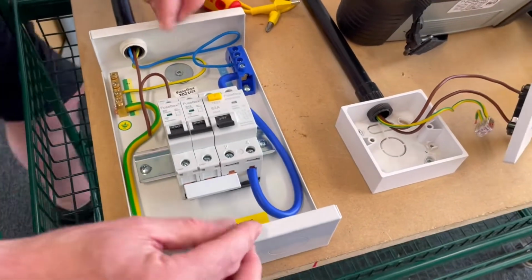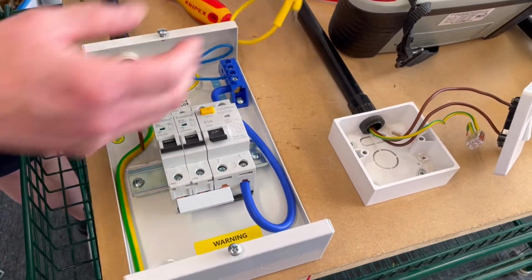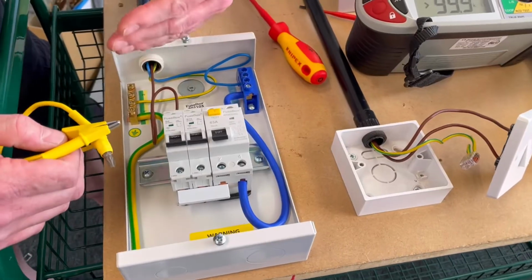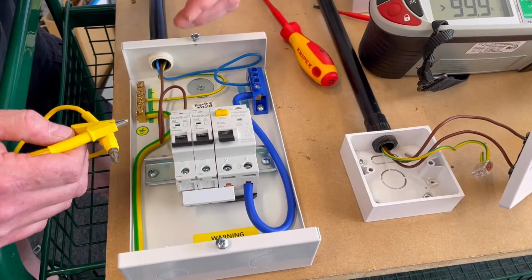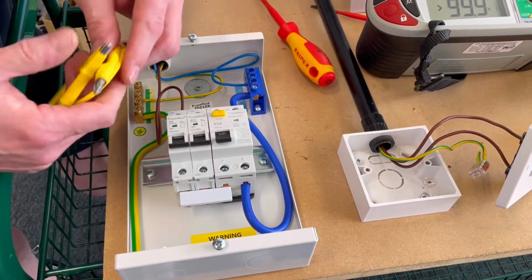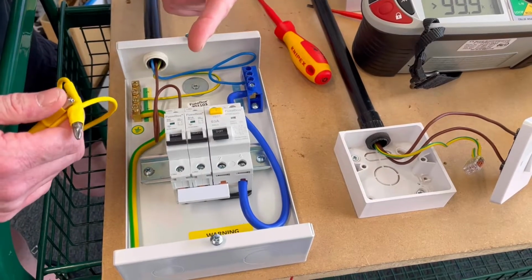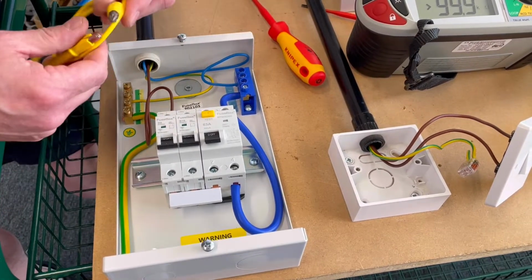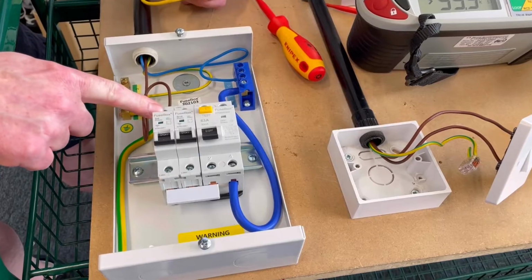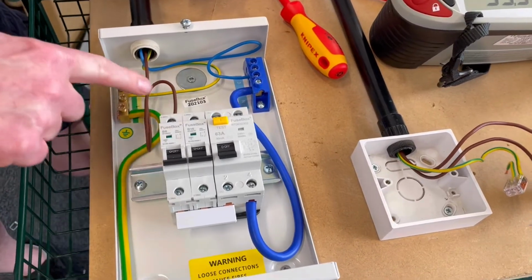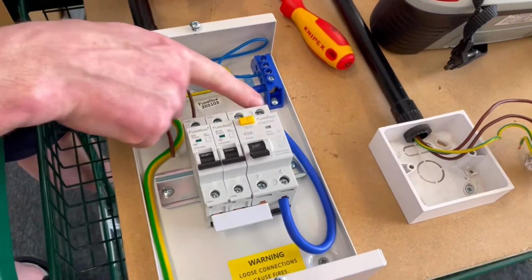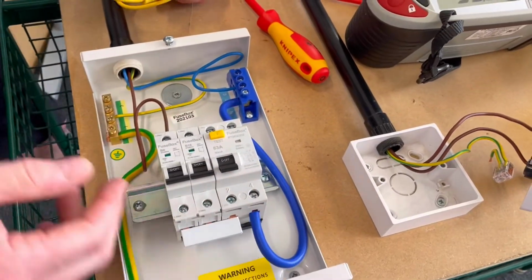So for this test, the continuity of the CPC, we're going to perform it where we also do the polarity test at the same time. So we're going to need to link together in the consumer unit the line conductor under test to the circuit protective conductor. So I need this circuit here linked to here. So it's a dead test. We've got no electrical energy in here. There's no cable, there's nothing, it's not connected to anything.